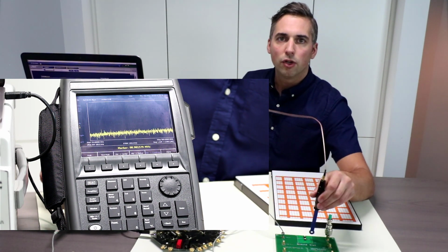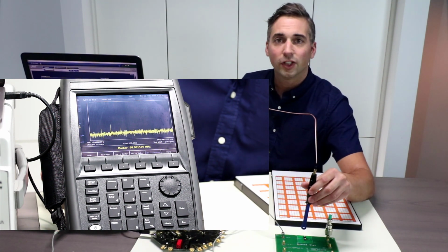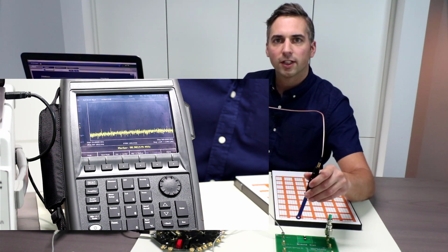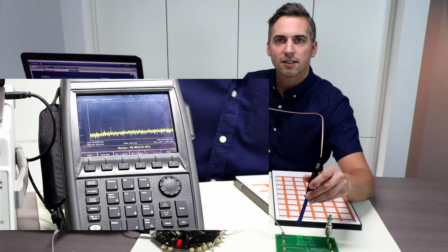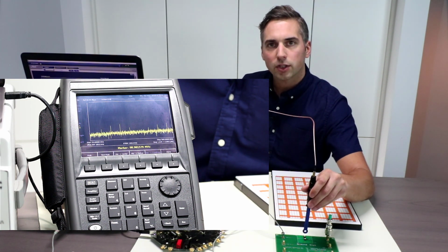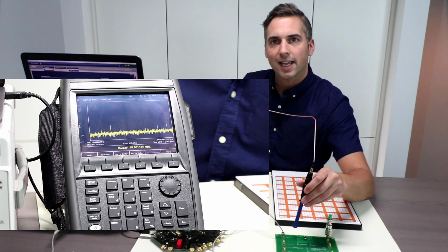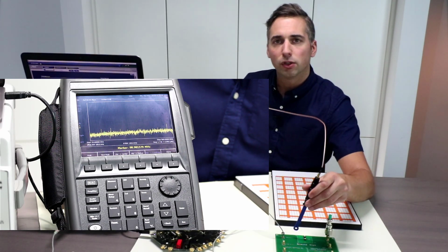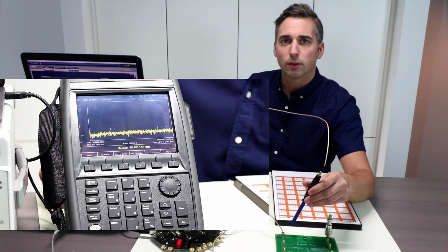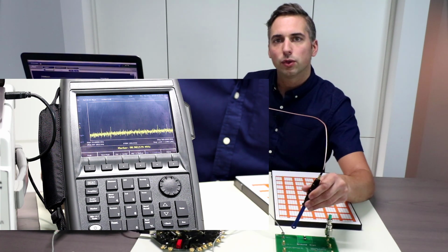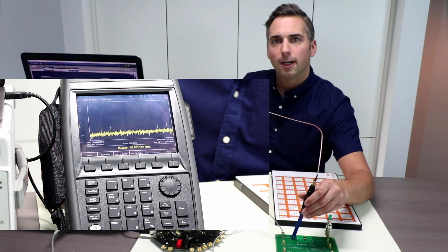So this is a big no-no. You want to avoid this situation at all costs. Now, on this board, we also have a couple of buttons that connect to the ground plane. It connects the ground plane much closer to the send path, and it allows the current to flow much closer to where it really wants to flow.